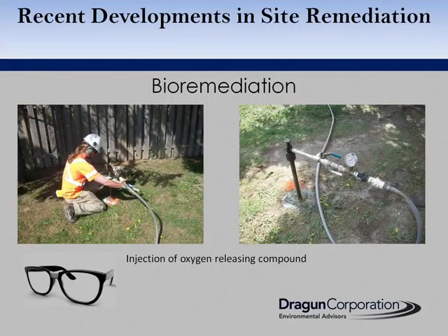And this technology was employed at the downgradient end of a plume near the property line to promote biological activity in the impacted groundwater that had migrated off-site. These types of injections provide a relatively inexpensive enhanced dissolved oxygen source that typically lasts between 12 and 18 months.